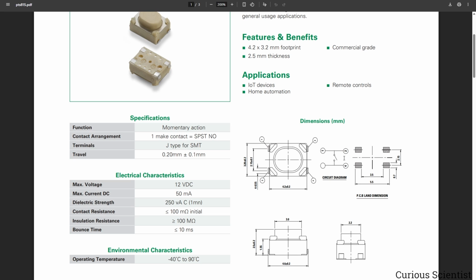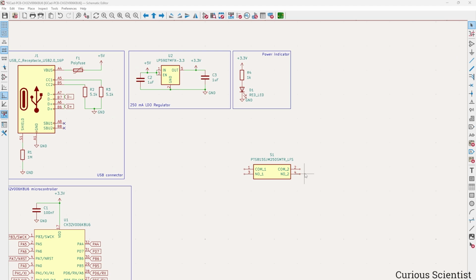So what I will do is that I will not wire everything on the schematics, but I will just use pin number 1 and pin number 3. How that will look is that I will first borrow a capacitor again, and I borrow the 100 nanofarad because we will need 100 nanofarad, and then I just put it in line with the COM1, and then I just connect it. I borrow a ground, and then I put it slightly under here because I need to run this pin to the ground. So this is done. And since I said that I'm not going to use the 2 and 4 pins, I just mark them as no connection.